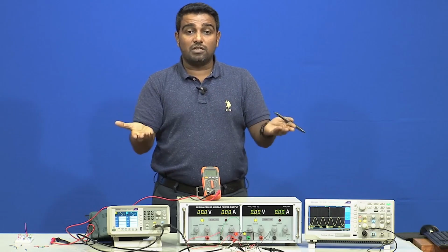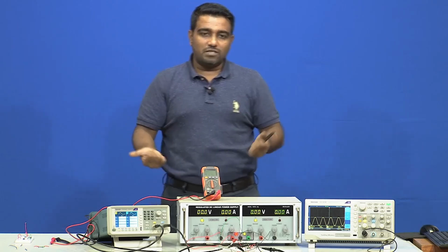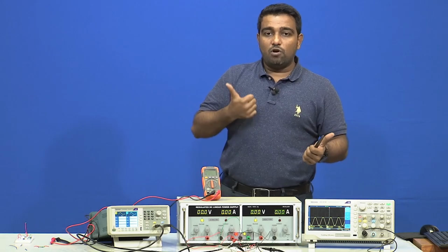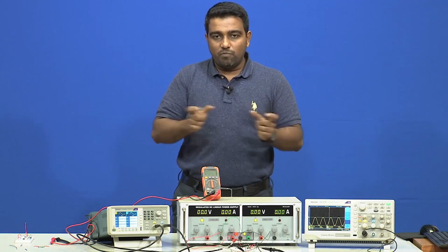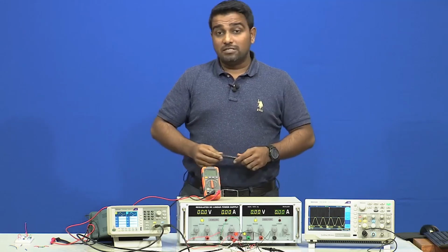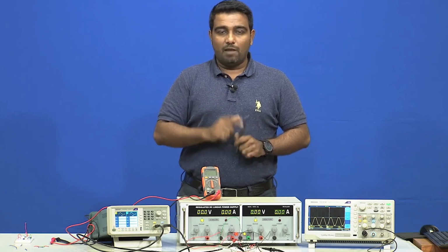Input signal and output signal waveforms would be the same, only there will be a change in the phase shift. In the non-inverting amplifier there was a phase shift of 0 degrees, in the inverting one a phase shift of 180 degrees. We have seen input voltage ranges, and now we have seen the summing amplifier. We have also seen the voltage follower or buffer or unity gain amplifier, right.